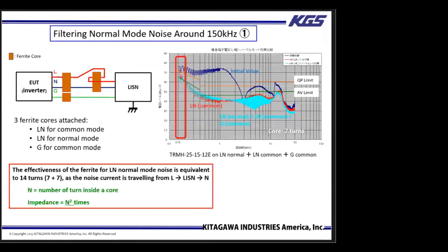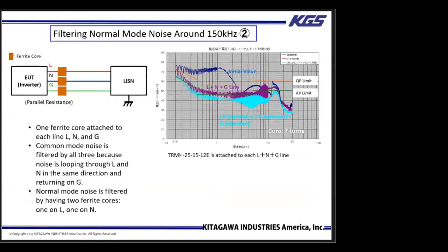As we previously mentioned, turning a cable through a ferrite increases impedance by the square of the number of turns. However, magnetic saturation should be kept in mind because the AC current is still being filtered, as opposed to only the signal noise. If magnetic saturation occurs, even if you increase the number of turns, the noise may increase instead of decrease.